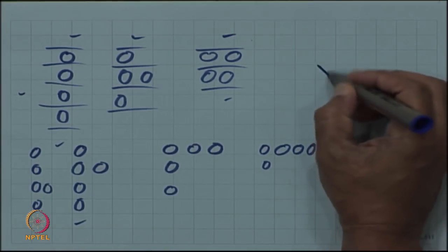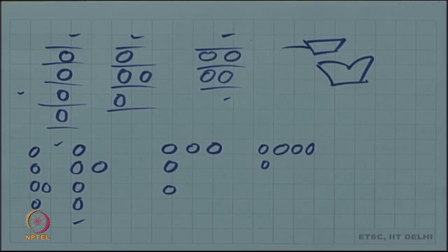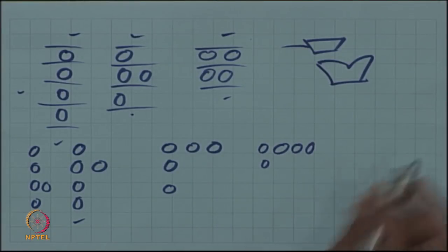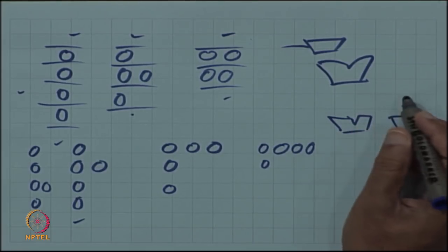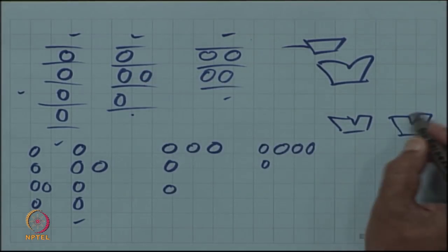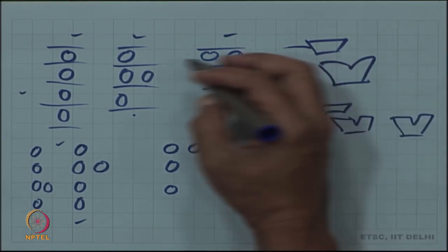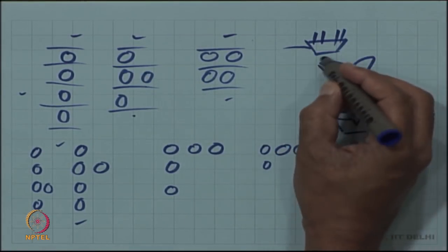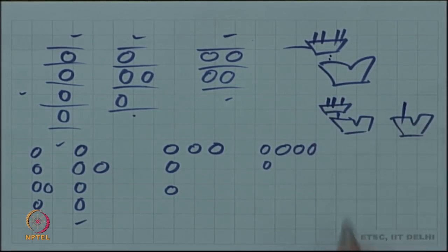That's my resource, and there is a mux here for which the select input is coming from the FSM. Actually, for this solution, you would have 2 different adders with muxes, maybe in the general case. The second one does not require a mux, but the first one does. So I think your point is that this one might have a 4 input mux, plus the registers that I need. This one might have a 3 input mux, because for the other one there is no select.